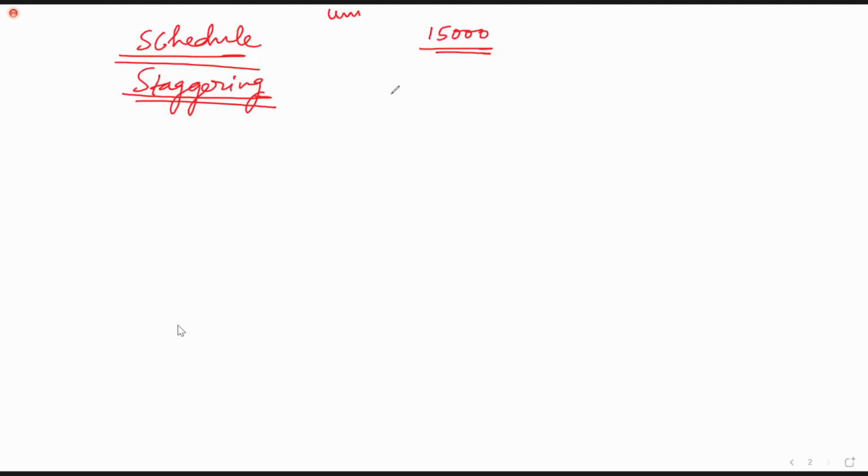So unit number one, you'll start opening say at 12,000 running hours. Unit number 2, you will see that yes, it has to be done at 14,000, or at 13,000, like this. And some of them you may exceed also because you can't open all the units at 15,000 running hours.